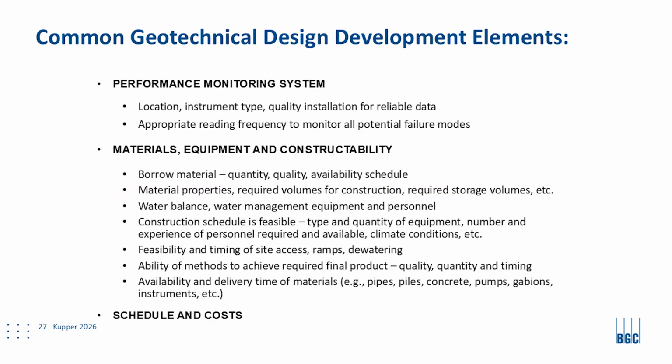So here I think we covered a lot of it here and there in different comments. But what is important here is that no matter how good your design is, you need to remember that the borrow material needs to be available, needs to be of the quality, and have the properties that you assumed in your design. They're not too clayey, too sandy, too wet, so that you get the quality and the quantity that you want. And it comes at the time that you want.